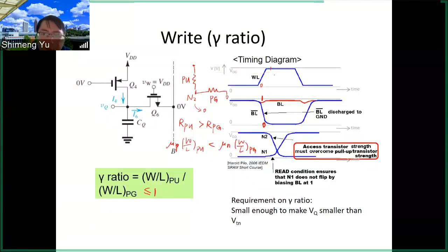And then the process will happen as we discussed earlier. So the N2 node will first have the 1 to 0 transition. So the N2 voltage will have 1 to 0 transition first. Till the N2 voltage decays to a small value, then the N1 0 to 1 will happen later. So you see this 1 to 0 happens first, and N1 0 to 1 will follow.